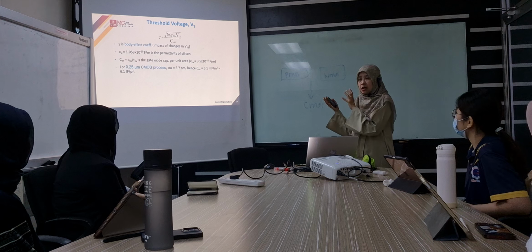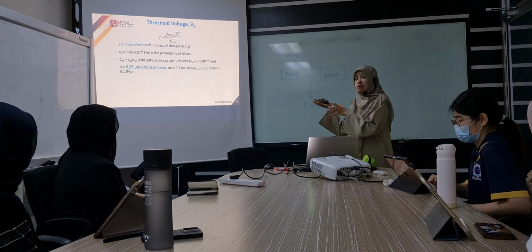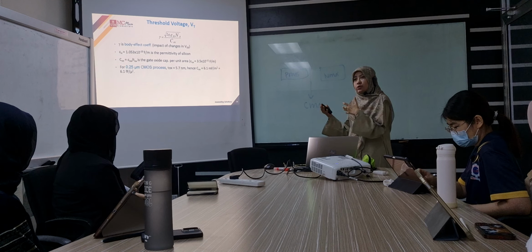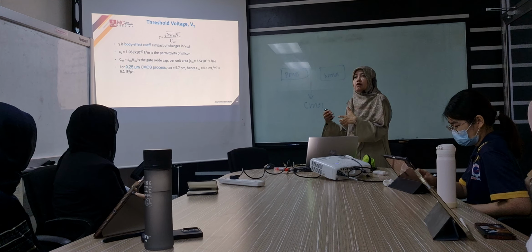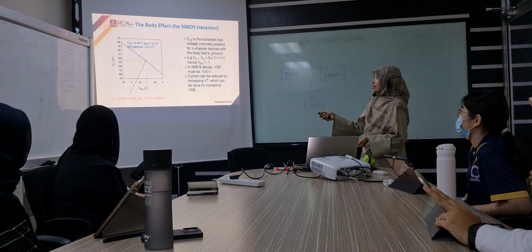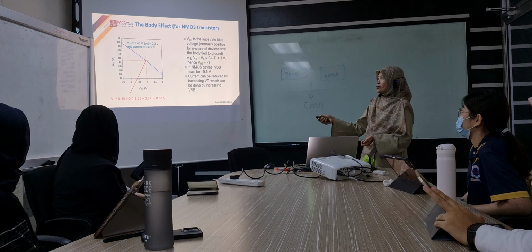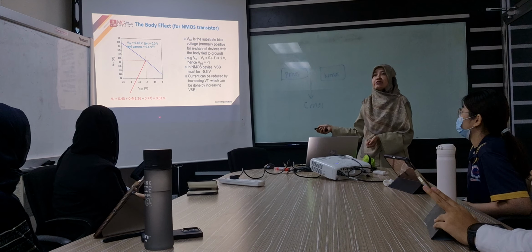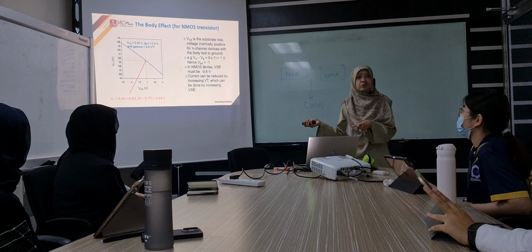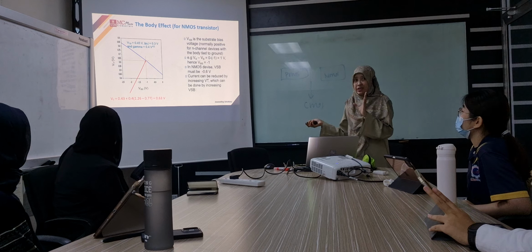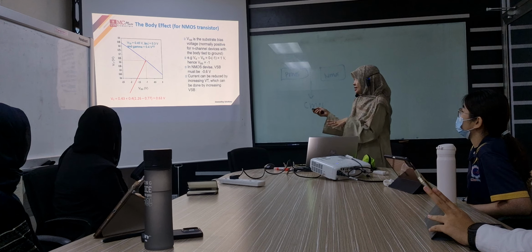Before we come up with MOSFET, there is oxide thickness together in the SPICE model, so we can estimate the oxide capacitance. For the body effect, it will increase the threshold voltage. It is at 0.43. When we come to the analysis, we will learn further about this.